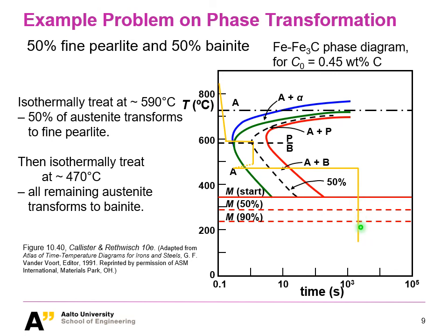That is not true anymore, because the martensite start temperature is of course temperature dependent only, so we just draw a horizontal line, but it is only available to FCC. Now, if you remember the martensite transformation mechanism, it is basically converting FCC to BCC, and that is a way to overcome the oversaturation of carbon atoms.